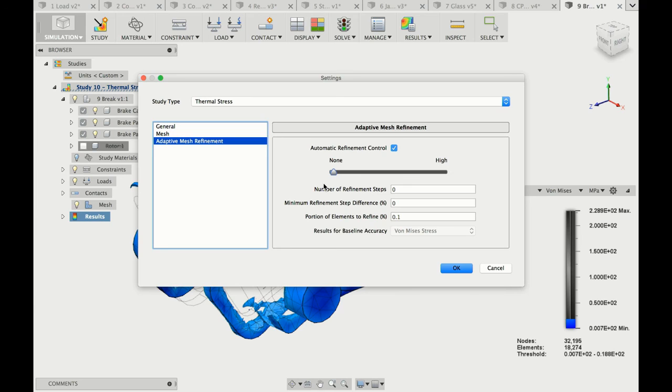And there is one nice thing that I actually didn't show today, and that's the voxel mesh we are using in case there is an issue with the mesh. With the traditional packages, if the mesh fails, you need to go back and simplify your model. You need to fix the model, actually change your model to help the software generate the mesh. Here we took a different approach. If the mesh fails, we switch to the voxel-based meshing. That's a different algorithm that does a mesh that maybe doesn't perfectly cover the body, but it bridges the areas with issues.